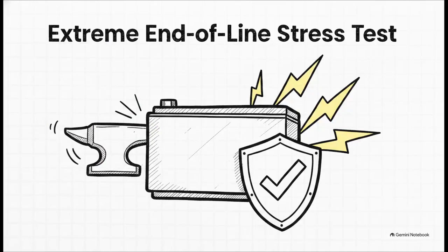The last line of defense is end-of-line testing. By hitting the system with a massive step current pulse load, we can intercept micro-ohm level resistance defects with 100% accuracy. And they follow that up with a 2500-volt DC hipot test for 60 solid seconds. Leakage has to stay under 1 milliamp, which absolutely guarantees safety before that battery ever gets anywhere near a customer.